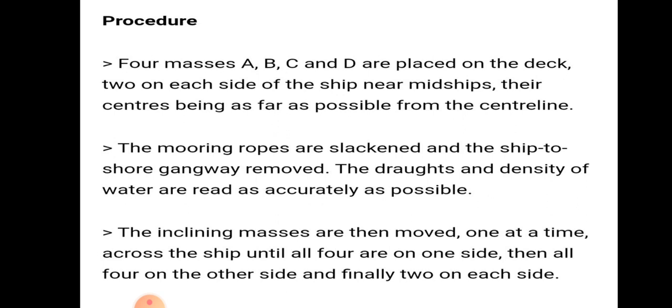Now the procedure for conducting the inclination experiment. Four masses A, B, C, D are placed on the deck, two on each side of the ship near the midship, and their centers are as far as possible from the center line.